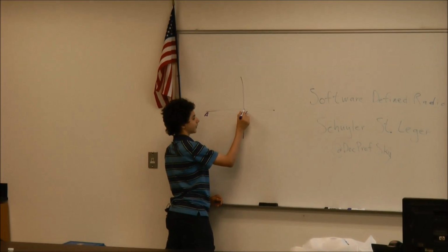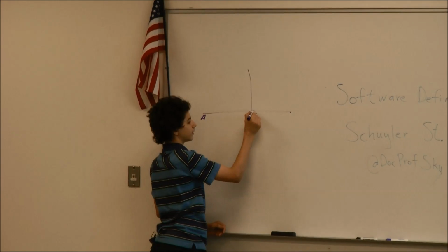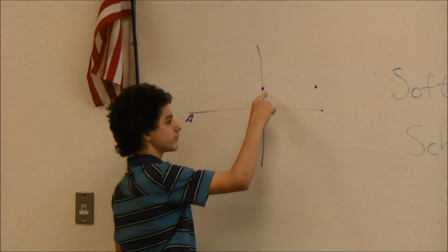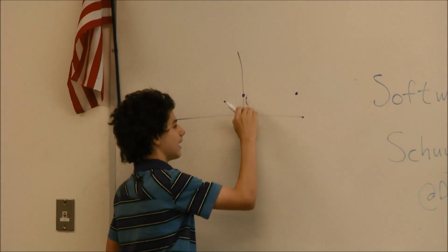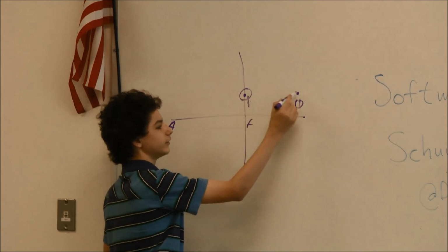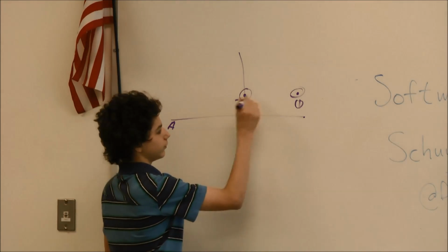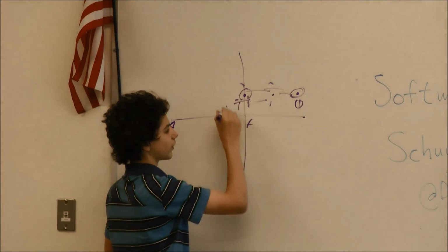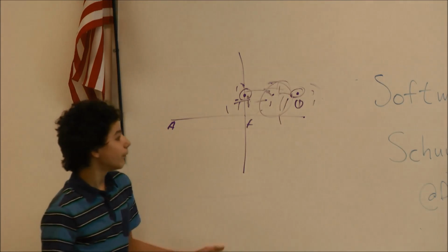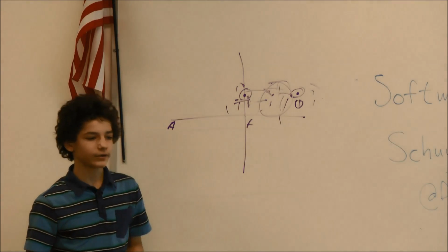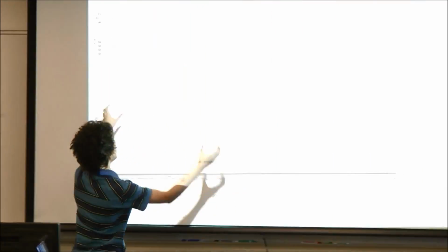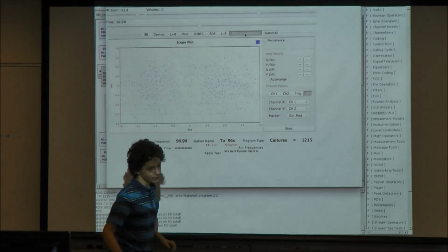So what we'll do is we'll say when the frequency is so much and the amplitude 0, we'll put it here. And then this is another data. So maybe this is a 1, and this is a 0. In a constellation plot, you want separation between your data points. If you have a lot of bad signal and your points for 1s are received like this, and your 0s are received like this, you really have no separation. So this could be either a 1 or a 0. In this case, the constellation plot isn't too good. You can see there's supposed to be 2 things here.